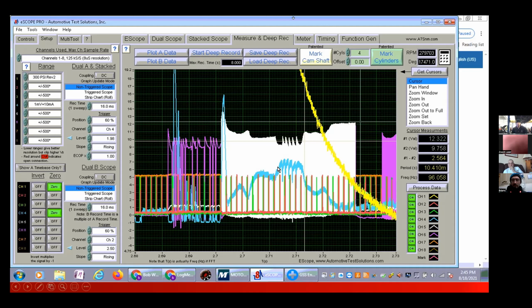But when we saw this, your mind told you right away, Adam, that is too logically based looking to ignore. Something's going on with this PCM that's throwing it into either a reset mode or a try it again mode. And lo and behold, when we looked at the data sheet, what I'm trying to get across to the techs that are on with me today is that the manufacturer and all data, and sometimes even Google, are not your only resources. I mean, Google was a resource in this case because we looked up the data sheet on it.